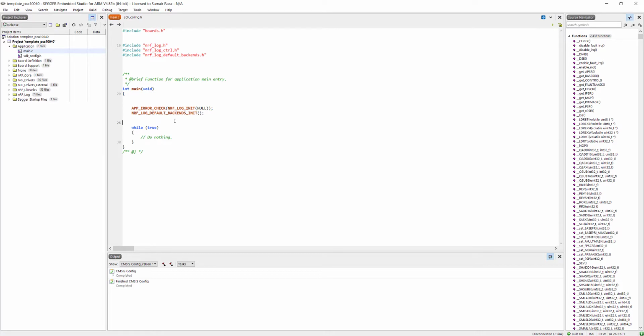In the deferred mode, our logging data is saved in a buffer, and it's transmitted when our controller is going into sleep mode. So this method is really efficient because it doesn't use the processor while it's working on some other stuff. But for now we don't need to go into much detail for that, so I'm just going to disable the